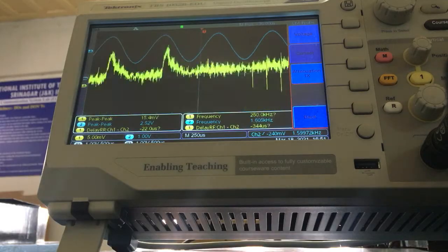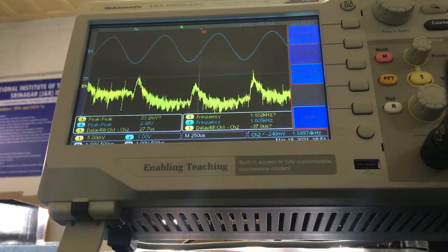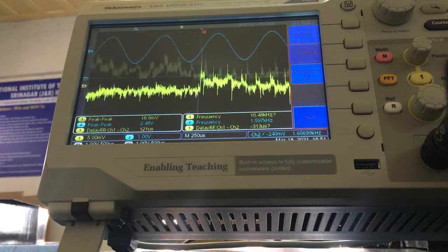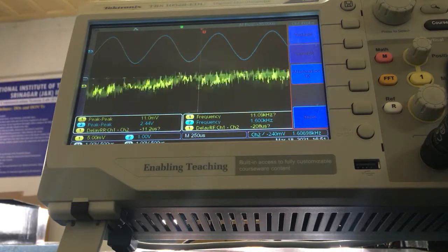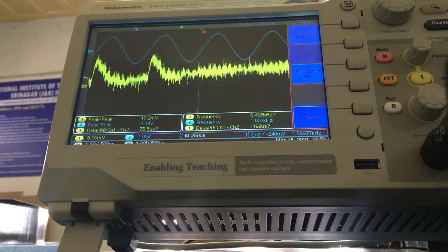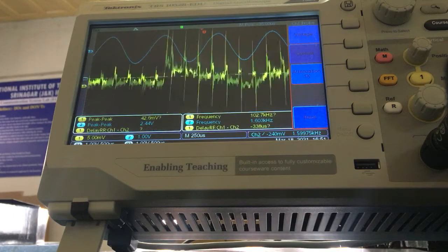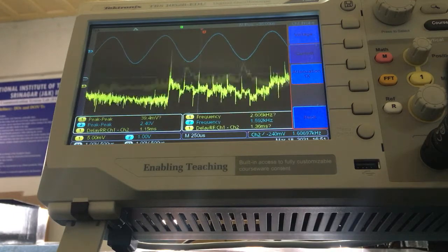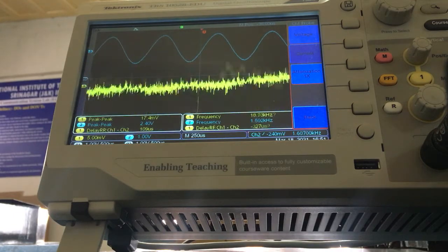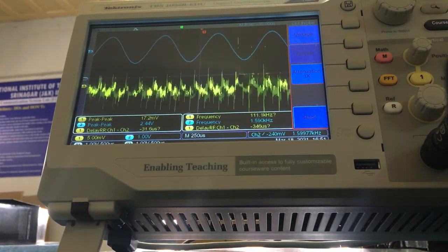Okay, now is the time to see the waveforms on the receiver's kit. At the top in blue is the transmitted signal, which is 1.6 kilohertz over the carrier of 1 megahertz, as you know. The waveform below is the direct signal received by our antenna, which contains a lot of noise plus all the frequencies present in the environment.